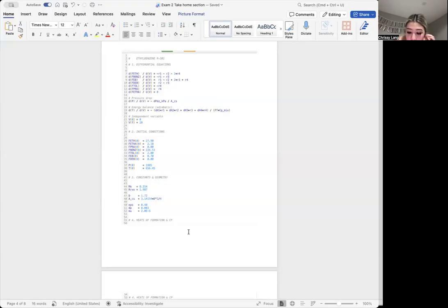From the outlet flows, I calculated benzene conversion and the selectivity of ethylbenzene to the undesired products like diethylbenzene. Then I compared my Polymath outlet values and reactor outlet temperatures to the corresponding values in the textbook. The trends match. Benzene is largely converted. Ethylbenzene is the main product. Some diethylbenzene and other byproducts form. The temperature rises due to the exothermic reactions, and the pressure drops along the bed.